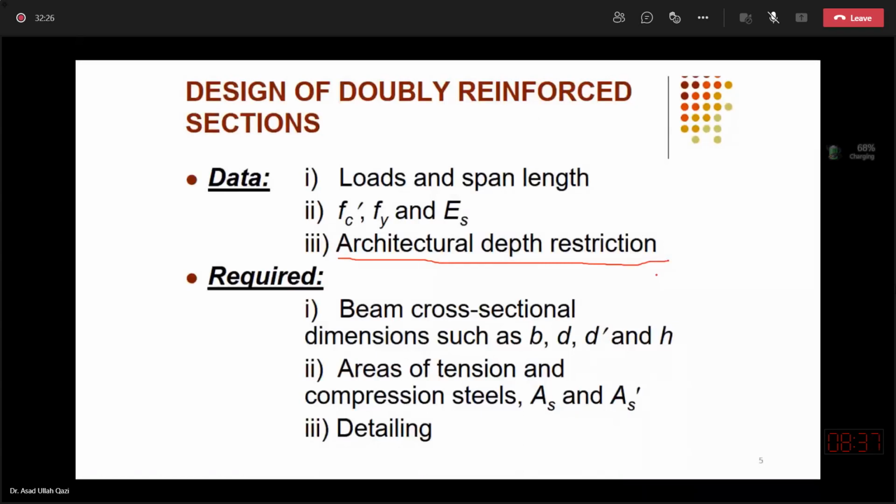As a structural engineer, you have to decide the structural system, whether it will be a one-way or two-way slab system, whether you will go with the primary beams only, or put some secondary beams on the primary beams, and the primary beams will act as spandrel beams for the secondary beams. So if this work is done, and now you know that finally the slab system is two way, then